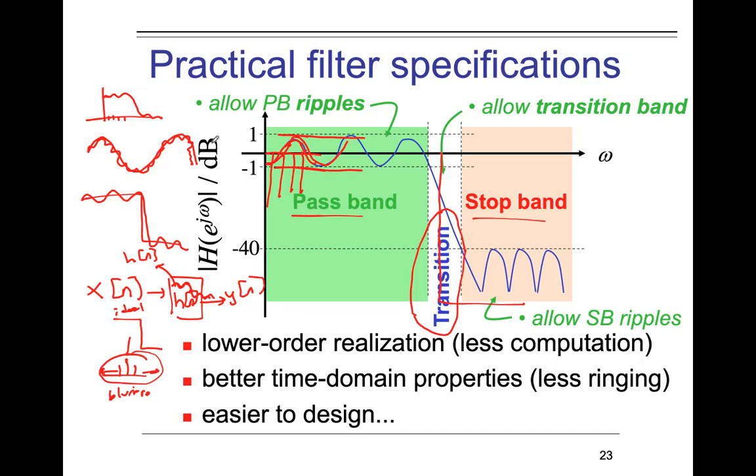In terms of time, the bad effects like ringing or blurring will be better, okay? We will get rid of, or we will have less, ringing effects. I mean, before, if we have an ideal filter, we get the sinc function. What about its time function? If you remember, arkadaşlar, usually these kinds of filters are not FIR filters. They are IIR filters, okay?